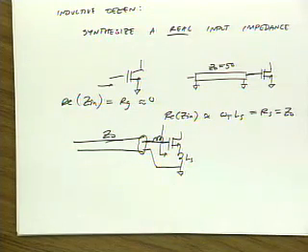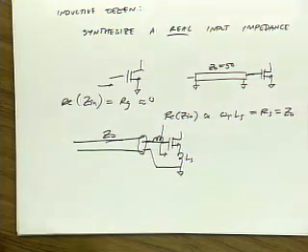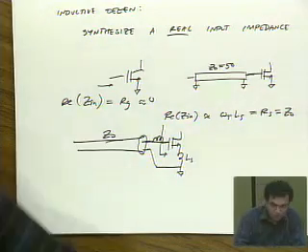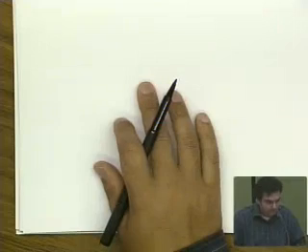Okay, so we analyzed the problem using series feedback. Now I encourage you to go and analyze a problem with shunt feedback. Use the Y matrix, use all the equations that we've derived, and try to derive the maximum gain you can get with shunt feedback, derive under what conditions shunt feedback is stable, and so on and so forth. Okay? So that's a follow-up to homework number 1. Maybe it's a good first problem for homework number 2. Okay, we're going to start a new topic now. Before I do that, take any more questions.